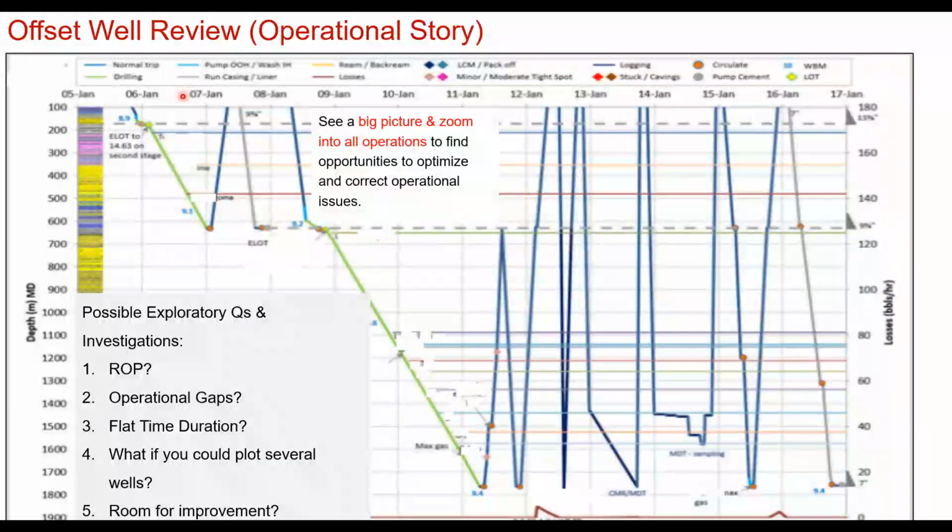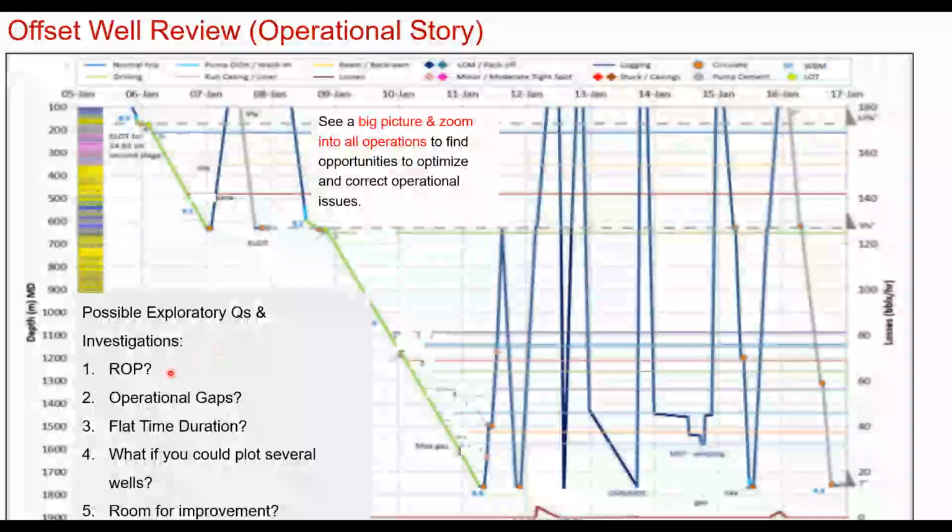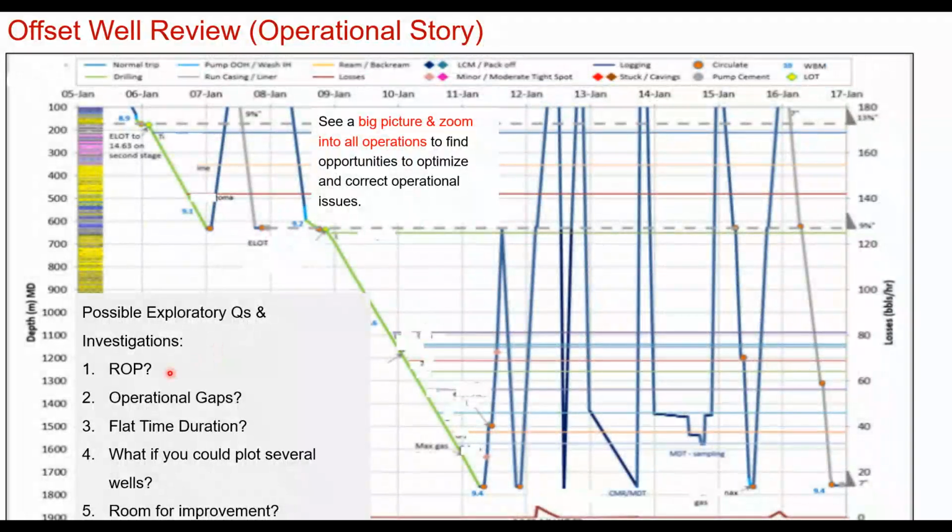For example, this is just for showing you this plot. This plot is telling you an offset well. Suppose you are interested to see what happened to one of my offset wells. Can I learn from it for your geothermal well, for example? You can plot them only bit depth and the time, hole depth and the bit depth. So you plot only three things.